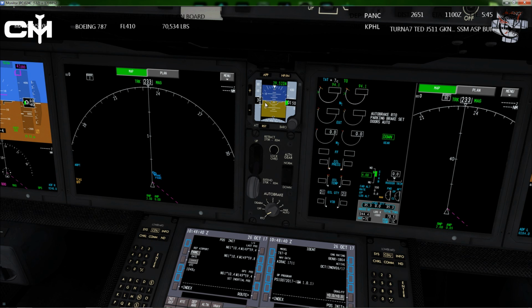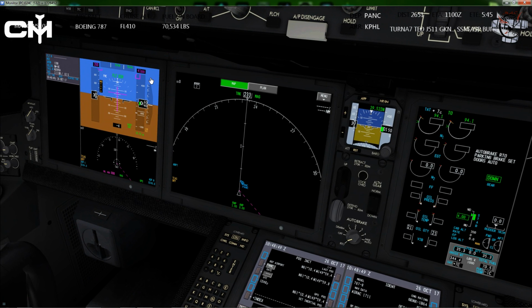We also want to make sure that our, my brain doesn't want to work now. Integrated standby flight display, ISFD. This needs to basically match this right here, at least where it makes sense. So there shouldn't be any approach information. If you click on that, you see the approach bars. That shouldn't be on. The altimeter should be set. We could change it between hectopascals and inches. Obviously, we're going to leave it on inches. And then what else does it say? Verify that the flight instrument indications are correct. So same thing, that it shows straight and level, which it should.